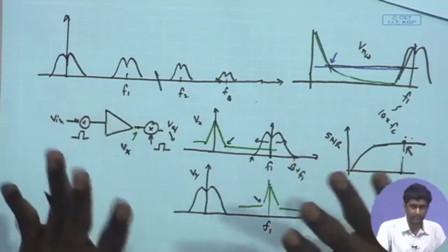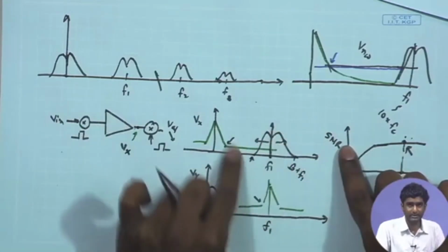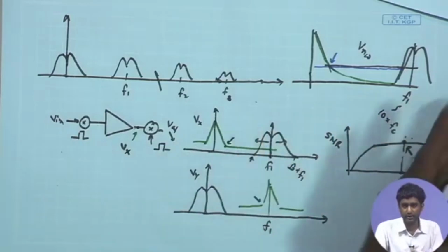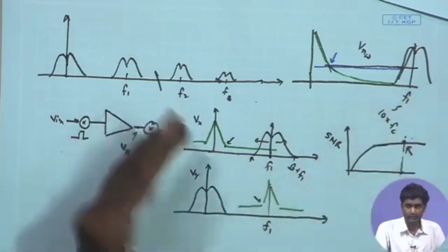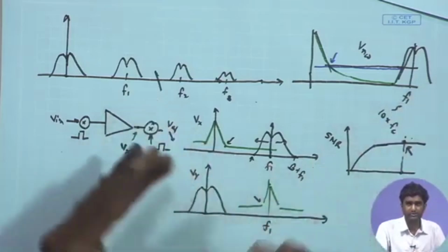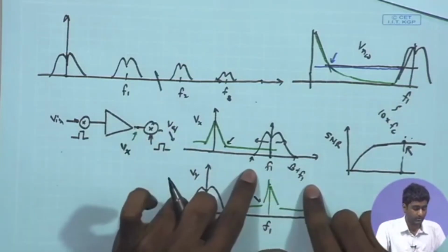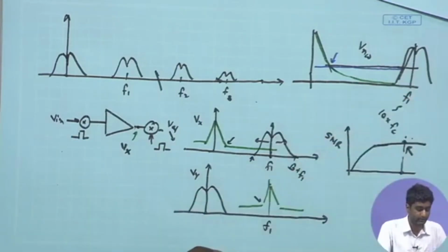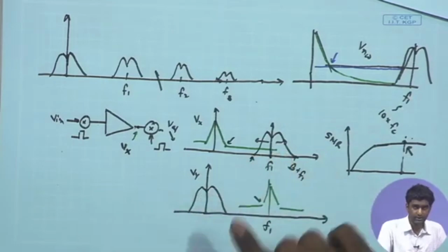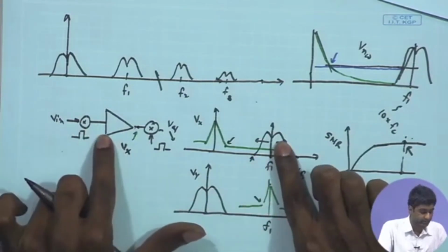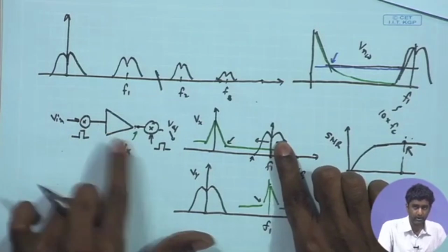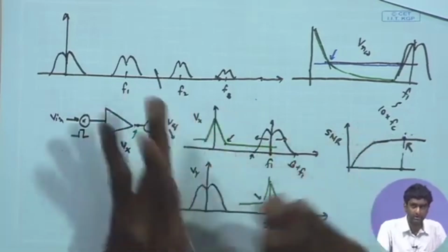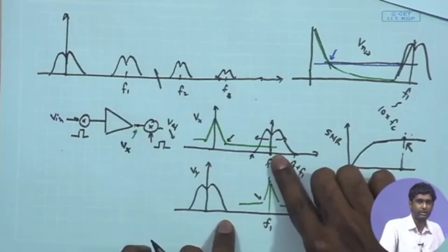the amplifier now needs to cater to this higher speed or faster signal, and hence its bandwidth must be much higher. And we know that if the bandwidth is supposed to be higher, we are going to have again conflicting constraints coming from the gain side. You have the thermal noise also, which is going to be impacted if you are trying to increase the bandwidth. So, larger chopping frequency necessitates higher bandwidth of this amplifier. Earlier it was operating in the baseband and the signal content was within 100 hertz. So, we would be happy with even 100 hertz bandwidth,